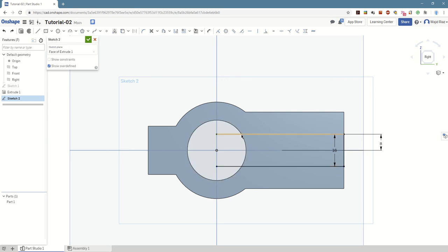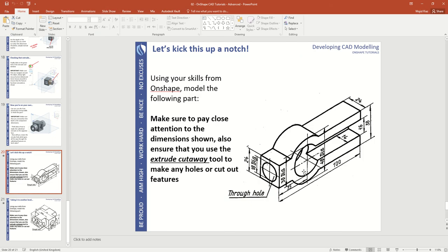What we need to do is include this sketch on the current face or plane that we're drawing on. And this also brings me onto another tool here, which is called the project tool. So in this particular case, rather than having to draw a circle again, which would be very easy to do, might I add, just by clicking there and then typing, what was it, 34 I think, was that 34, was it?